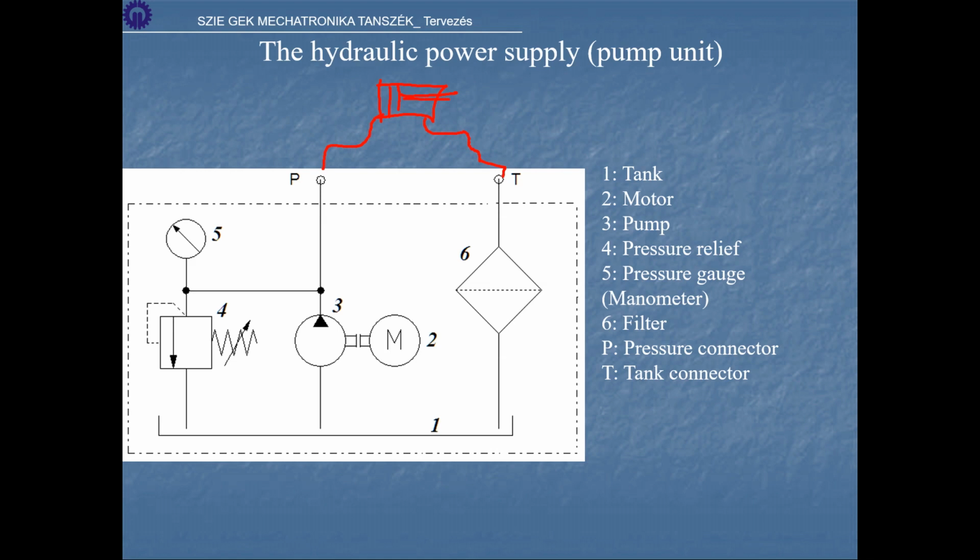And if it reaches its end position, so here, then the piston will stop, and here a very big pressure will be accumulated, because if we have a constant Q here and it can't flow anywhere, the pressure will rise, and in the end of the day there will be a rupture in the pipeline or whatever. So it's a very uncomfortable thing to have.